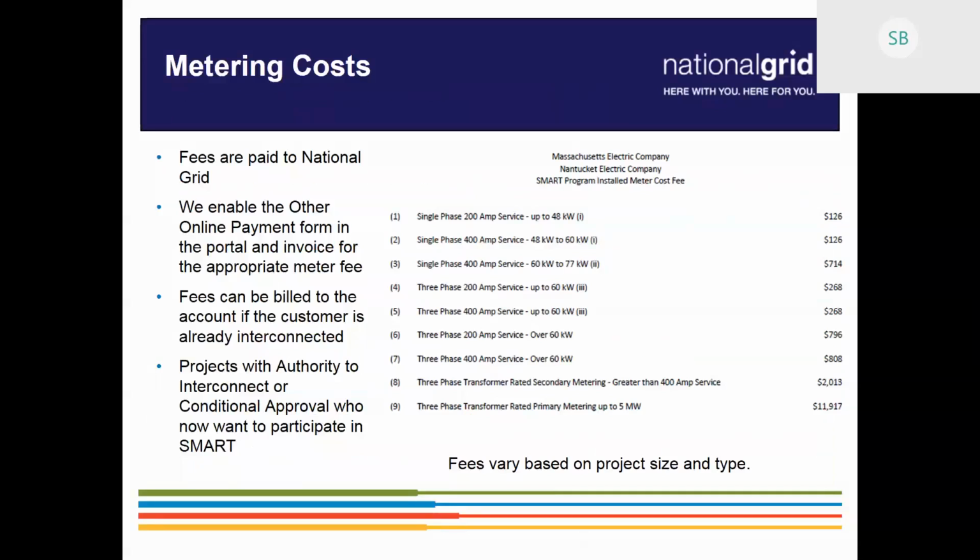So I believe the way the smart metering is set up right now is that we do end up needing 3 meters so that we know the total of what's actually being generated, what's being used for storage, and what's going to be at the total head of the site. So those would all be on the National Grid side. So it would have to be ahead of the point of common coupling. So having something on the customer secondary side of their transformer somewhere within their system, I don't believe is currently allowed with the arrangements we have.